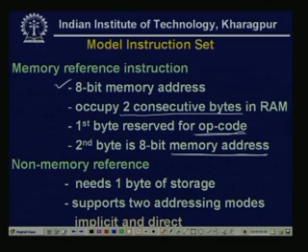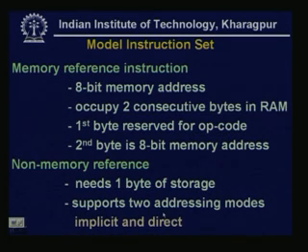The non-memory reference instruction needs only 1 byte of storage because it does not need any memory address, only the opcode. Now, this supports 2 addressing modes, one is implicit and another is direct.